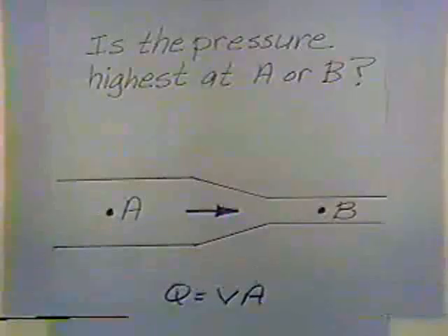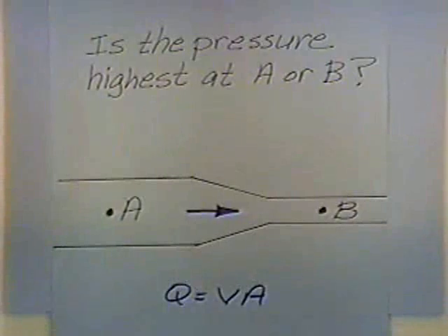But we know for sure that it still makes A an even larger pressure than B. And I'm assuming that in a short reach of pipe, the head loss may be relatively negligible. But even if we consider the head loss, it would make A have an even larger pressure than it would otherwise, relative to B. Okay.